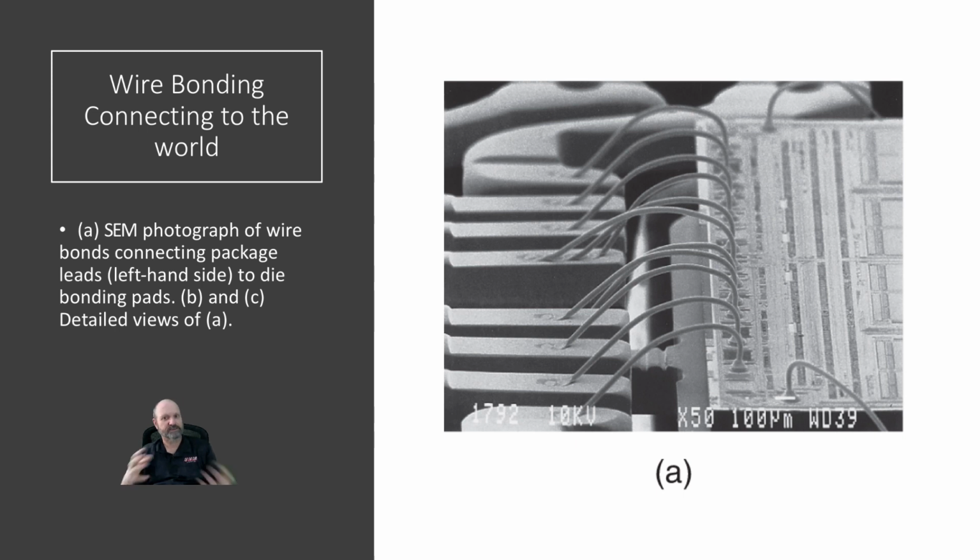That is what's inside the package, right? So you've got to connect from those metal pins that go in your circuit board to the computer chip itself. And you can see two different bonding techniques. On the left is wedge bonding, which is just pushed into the pin, and on the right is ball bonding. Probably ultrasonic, when you put a little pressure and some energy into it, and it fuses with the bond pads. So these are little pads that you connect to that are around the side of the chip.